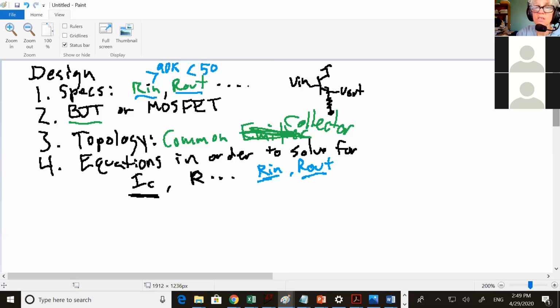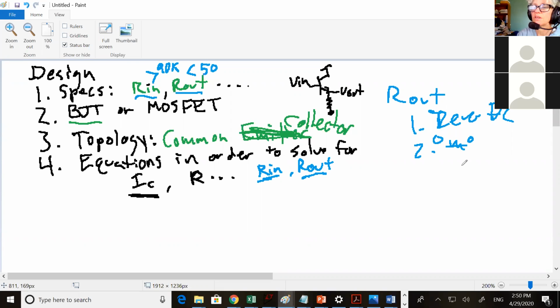One other thing is that when you do the small signal analysis to find R out, make sure to go through all the simplifications. So there's 0 DC sources, like, as you said. If there's 0 volts across a resistor, get rid of it. If VBE equals 0, then get rid of the current source.